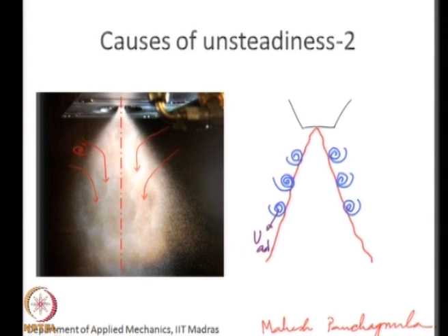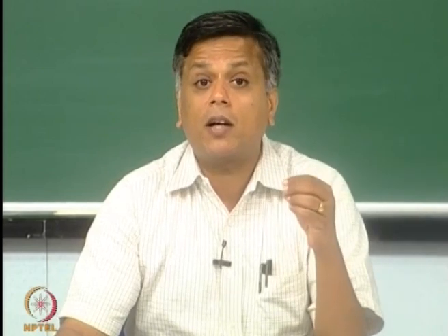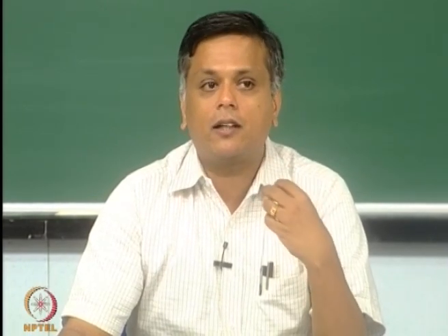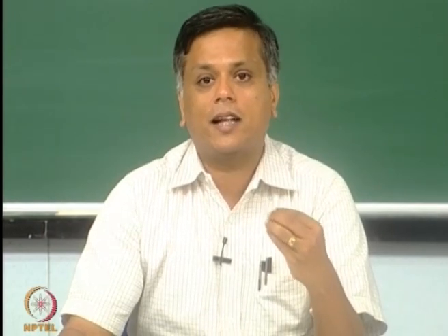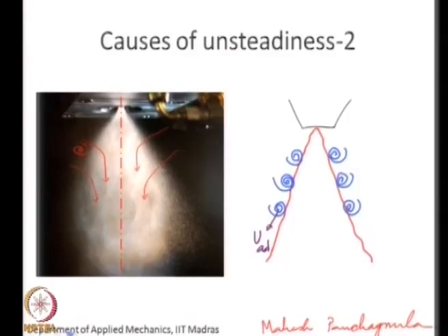When you have these vortical structures, the drops in the vicinity of the spray are going to interact with these vortical structures, and like we said, we already have a polydisperse collection of drops. So, if there is some kind of size dependence in the nature of interaction between a vortex and a drop, then different sized drops are going to react differently to the vortex, and that in turn could cause other nonlinear effects. So, we will see what this means in just a moment.